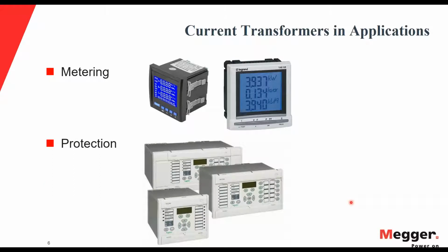The second application we have for current transformers is protection systems. The protection systems usually don't operate in normal conditions or normal values, for most types of faults or unusual conditions. Usually they operate in the fault condition, which is a number of thousands of amperes, or a number of times, 5 times, 6 times, 10 times your rated current. So their specified range is usually above your rated current range.